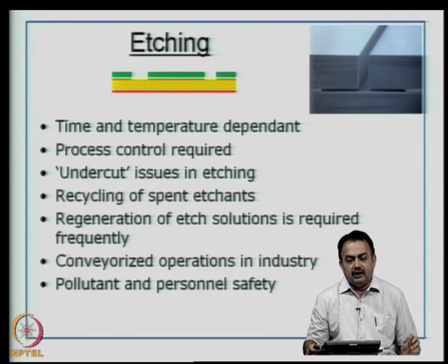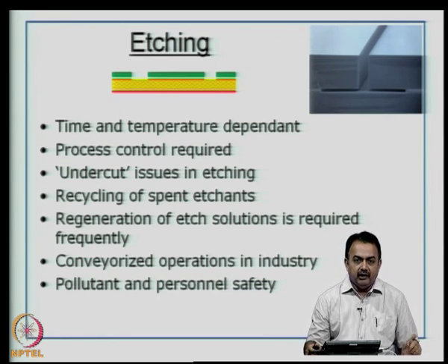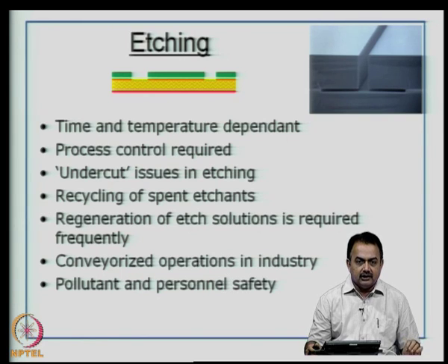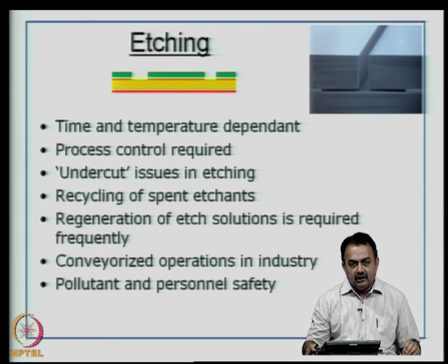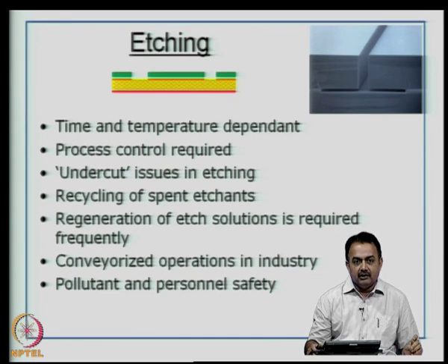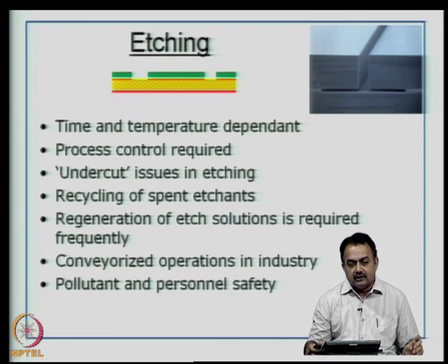If you take an etchant, let us say cupric chloride, you have to maintain suitable working temperatures for this cupric chloride. Then, if you are using machine based conveyorized etching, then there are other factors that come into picture that are based on the equipment, the machine. Therefore, those controls have to be taken care of. Maintenance is a crucial issue if you want to get very high performance etching, and especially if you are doing fine lines, of the order of 4 mils and so on.